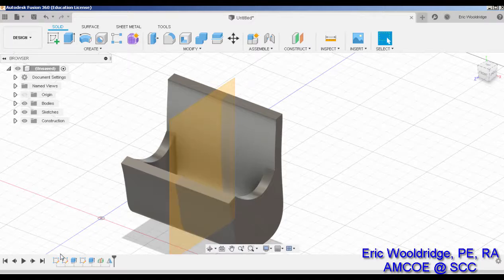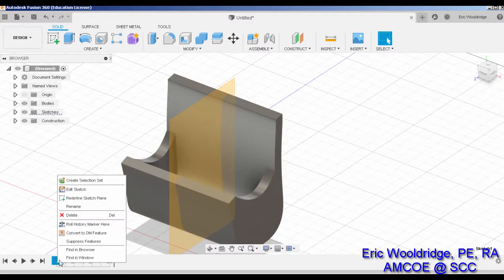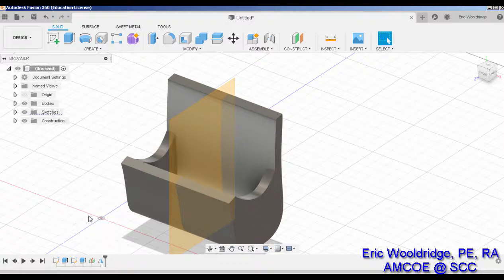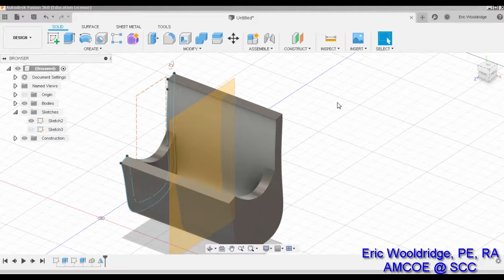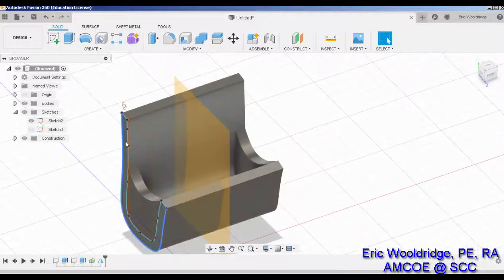Now you'll remember in my first sketch, I think I did an extra sketch I don't need here. Let's delete that. You remember our first sketch, I drew that circle, but you don't see that sketch anymore. Well, you can always turn sketches back on by clicking right here, and we can re-see our little point where that's supposed to be. Now, at this point in time, I want to actually sketch from this plane.